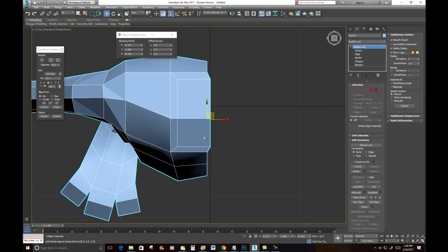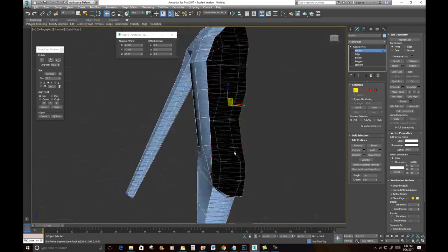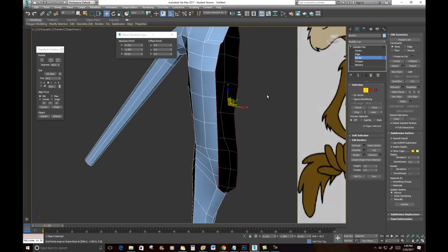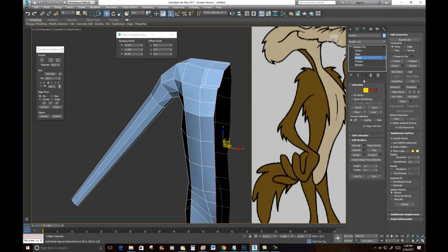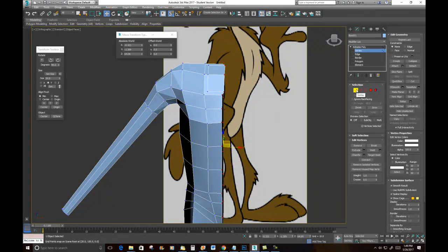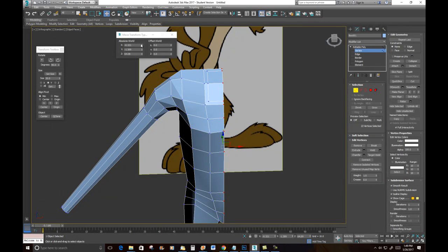What I want to do is get all of the center verts. So I'm just going to look and make sure I have them all. And if I wanted to actually make sure that I'm selecting them all, I could just get this open border, which would select them all. And then I'm going to control click here onto vertice. I'm going to hit S to turn off this snap so I won't get that yellow crosshair. And then over here, I'm going to say make planar on the X. And once those are all planar, then I'm going to right click here to center them on the X.